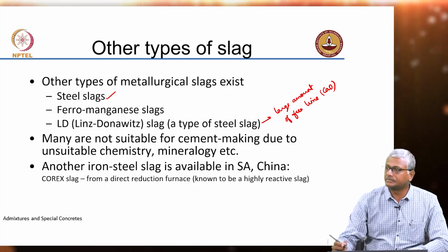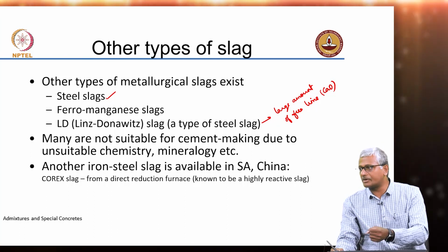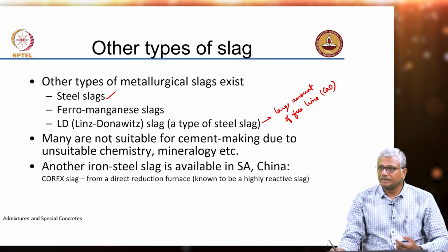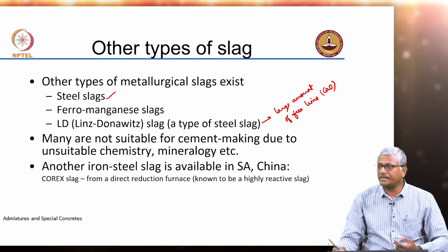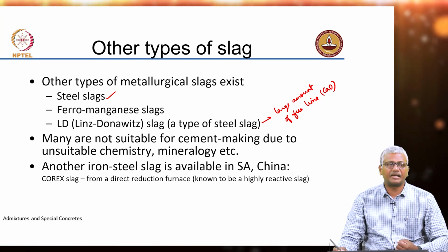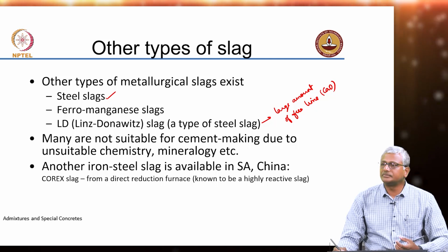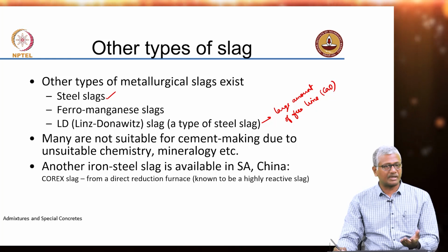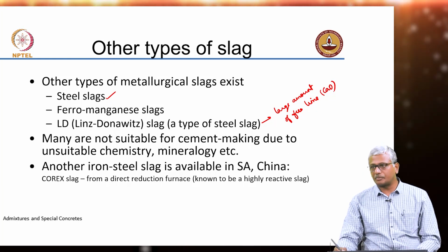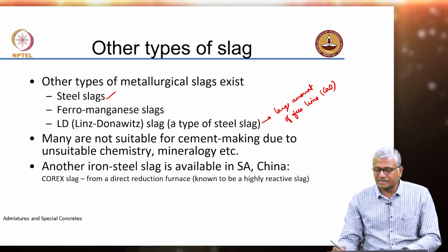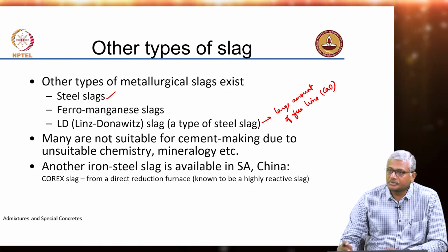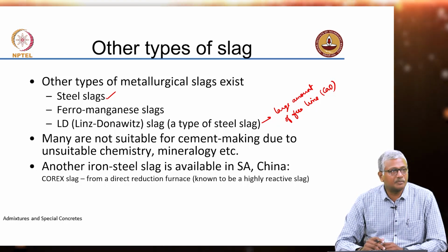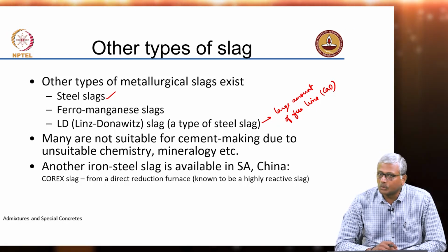Calcium oxide. If you remember, in cement we want to restrict free lime because otherwise it produces unsoundness, it produces expansion upon setting. So, this LD slag tends to have a high amount of free lime, and that makes the use of LD slag even as aggregate quite difficult. Air cooled blast furnace slag, you do not have that problem, but LD slag, the process involves production of the slag which has large amount of free lime. Okay, so, you have to be careful about where the slag is getting collected from and what kind of approach you may have towards utilizing it.